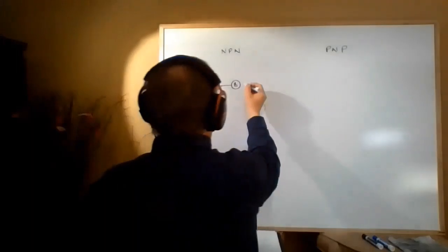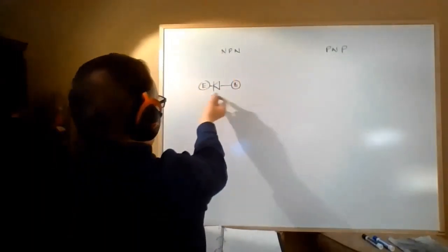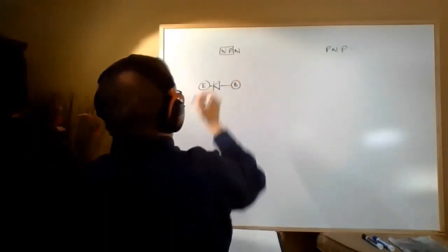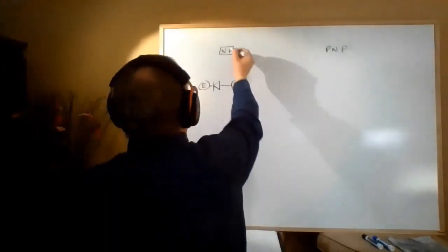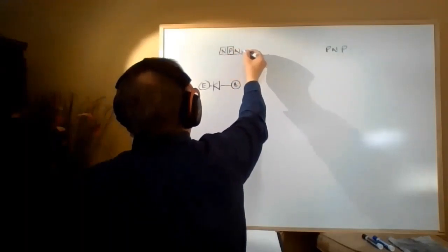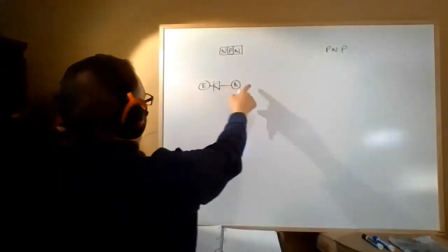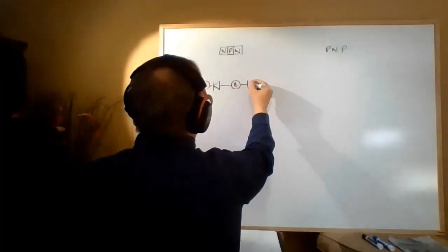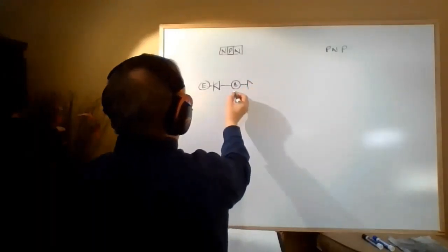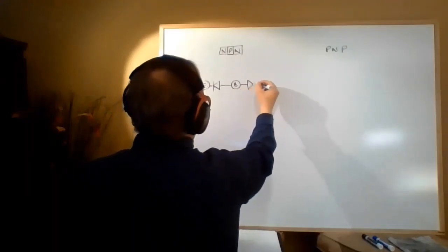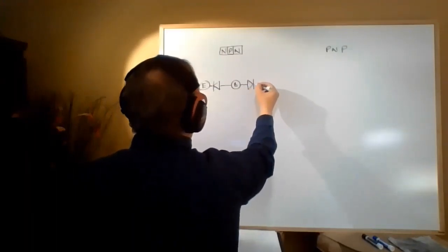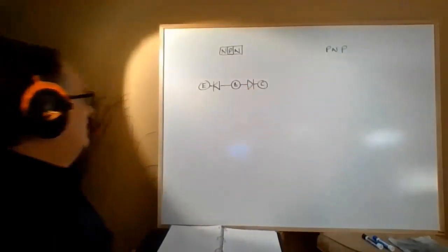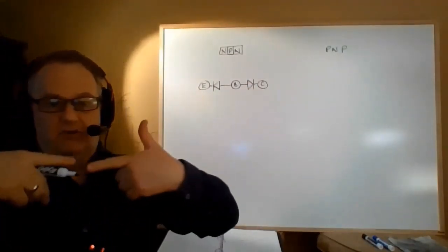And that's really just like a diode symbol, and that really applies to this, okay? Now the part that is not really drawn like this all the time, but what do you think the symbol looks like for this piece here? Well, it's exactly the opposite, because now you have the P-type material here and the N-type material over here. So this is like a junction going this way. And here you got the collector. So really you can just view it as two diodes that are inverse connected.